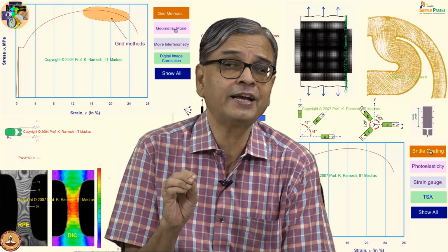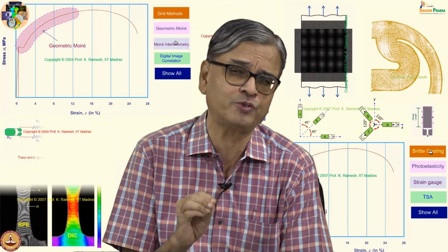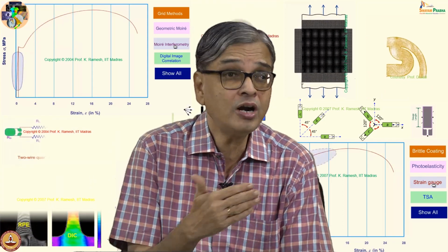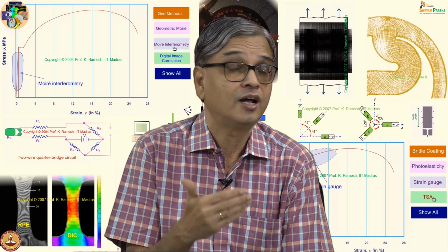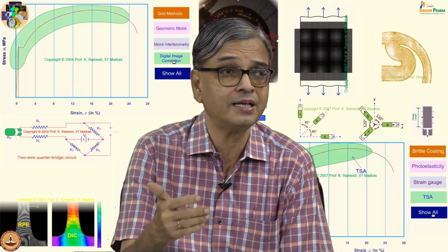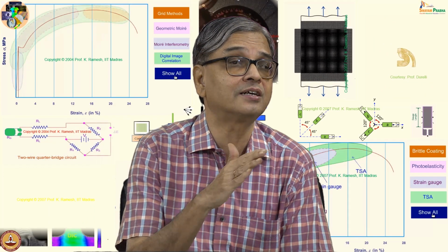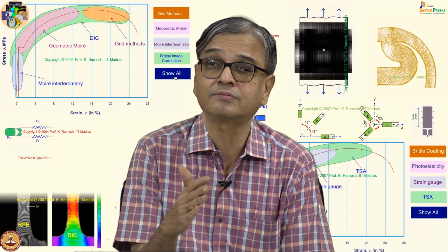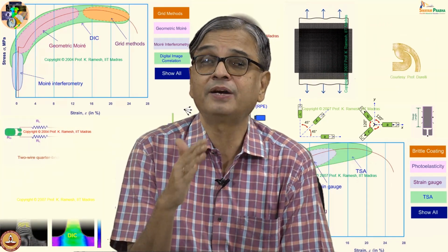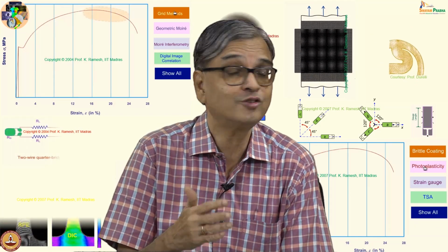But what you have to keep in mind is, technologically strain gauge measurement is very, very sensitive. You need high precision strain gauges. And how do you bond them? How to bond a strain gauge on a given surface on a prototype itself is a very important training a strain gauge measurement specialist has to undergo. And there are certificates given by the British Society of Strain Measurement. You have to renew that certificate every 3 years. So, it is not a simple job.